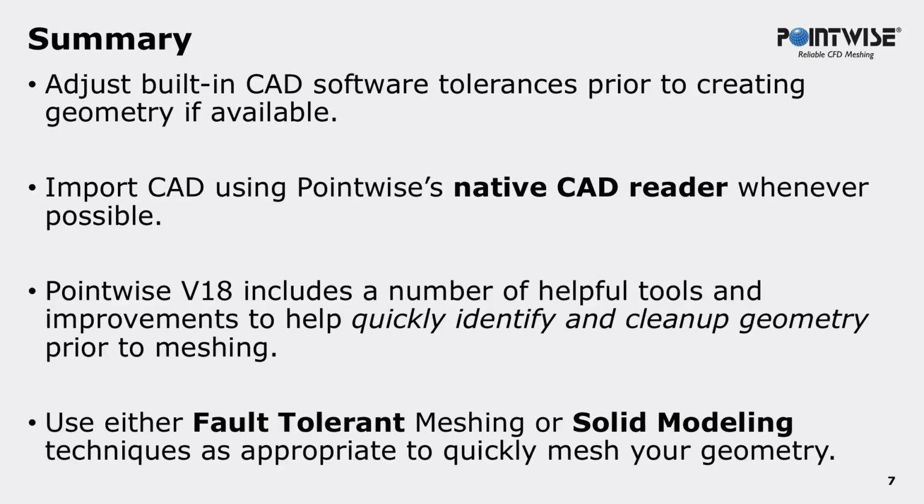In Pointwise version 18, there are a number of useful features that can help users quickly identify potential problems with geometry that has been imported. Pointwise includes a number of tools to repair flaws in geometry. Depending on how extensive this geometry cleanup task is, one can pursue either solid modeling or fault-tolerant meshing approaches to create a suitable surface mesh.